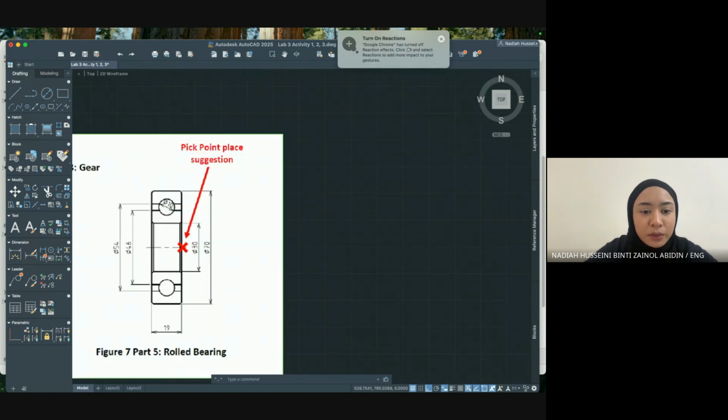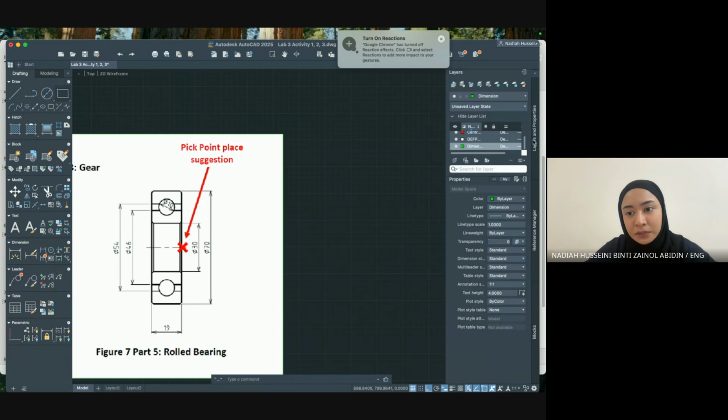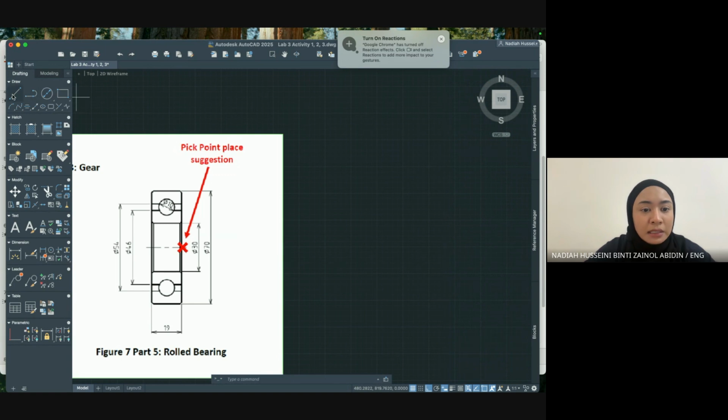Okay, so let's start with the outermost structure. That is how I roll, but you can figure out what works best for you. I'm just showing you the typical way to do it. So we need to work with the default layer. Make sure you are selecting that first. Double click on default layer or layer number 0, and then click on line.